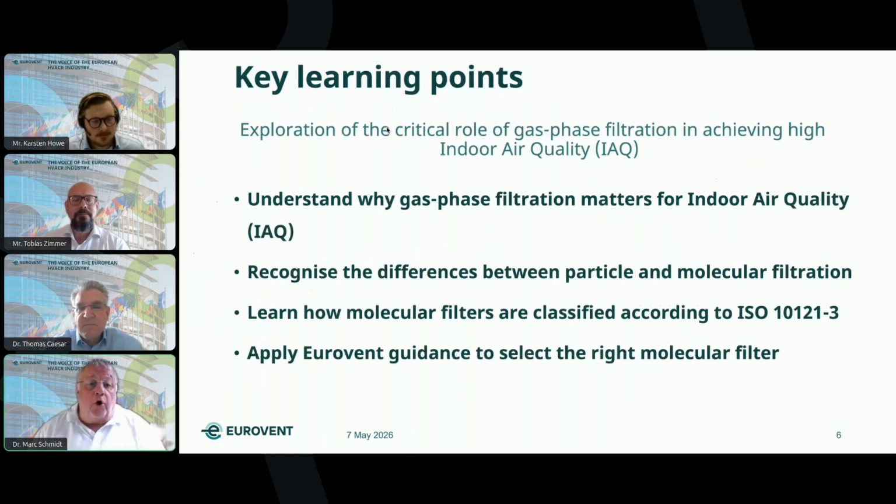The key learning points for today are to understand why gas phase filtration matters for indoor air quality, to recognize the differences between particle and molecular filtration, to learn how molecular filters are classified according to ISO 10121-3, and to apply Eurovent guidance to select the right molecular filters.